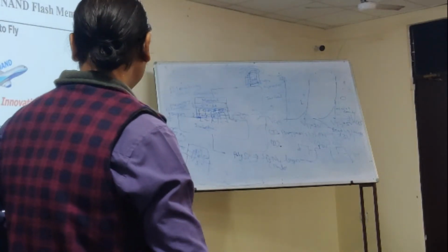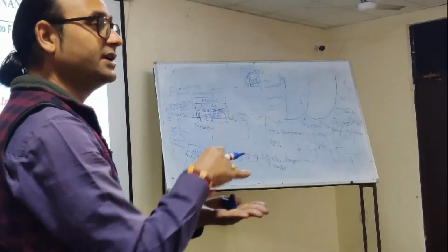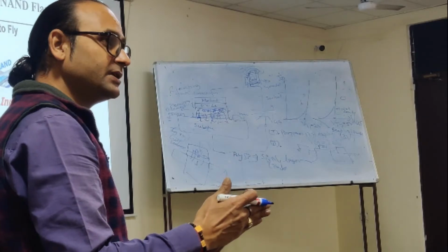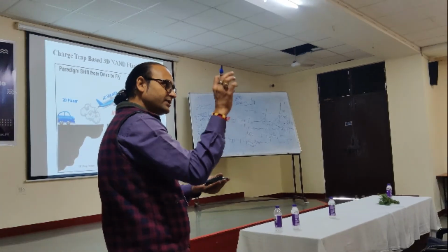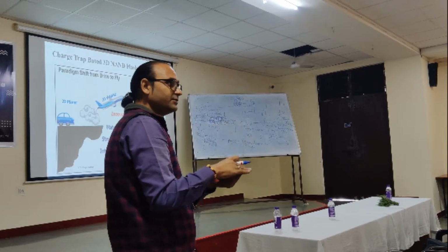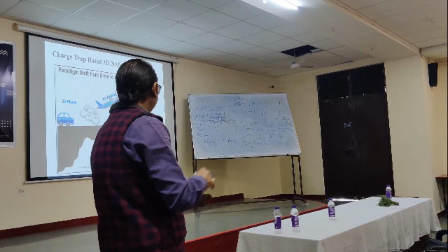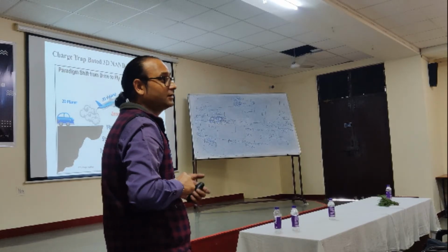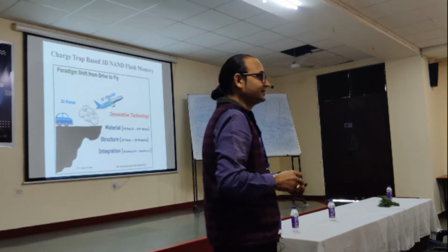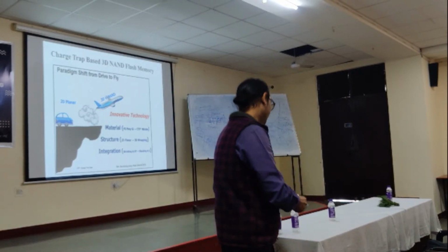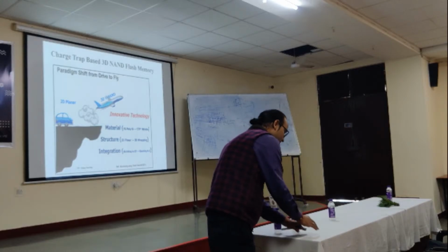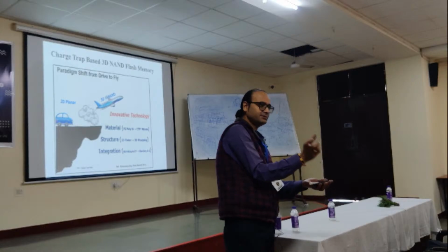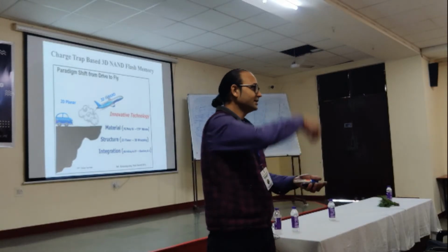And the most important was earlier we used to shrink in the XY direction, means planar only. Whatever is the space available to us in any chip, we were just scaling down in that area only. Now what happened, there is scaling along the vertical direction. I will show you how scaling is possible along the vertical direction. It seems very strange. Suppose this is wafer surface, shrinking along the wafer means in the xy plane is okay, minimize transistor size, we will get more number of transistors. How is this possible in z direction?